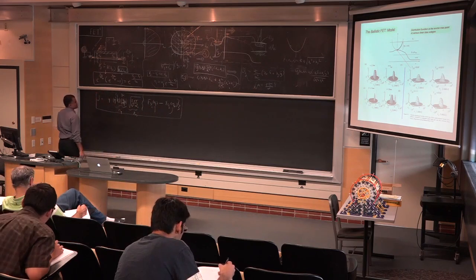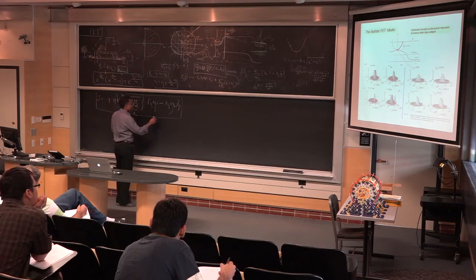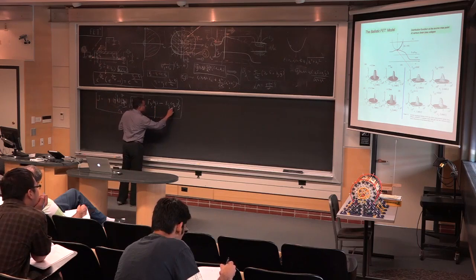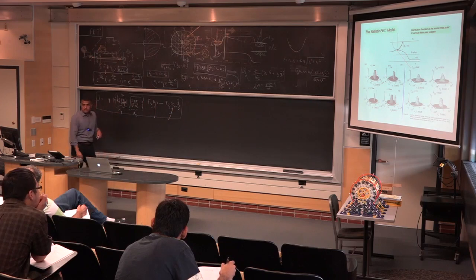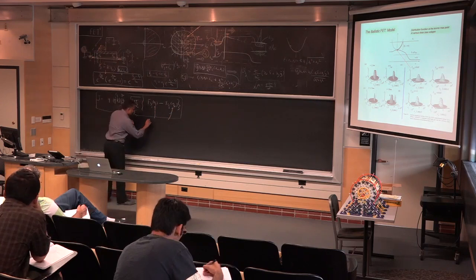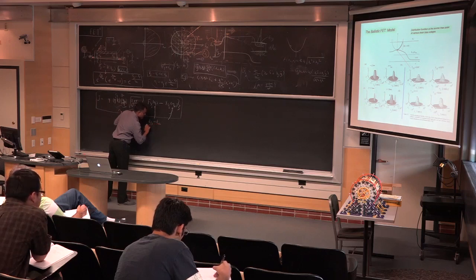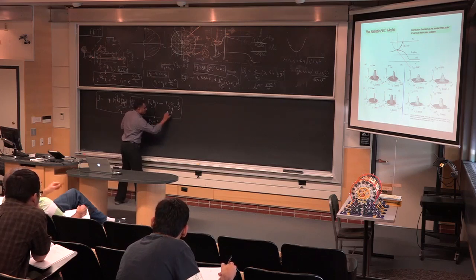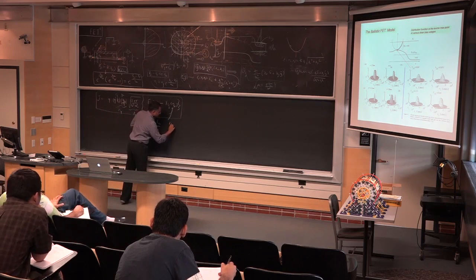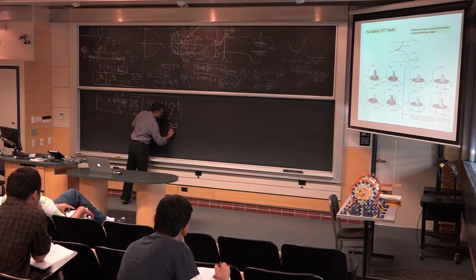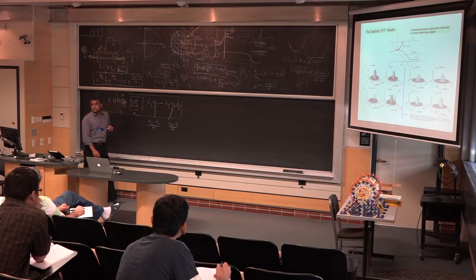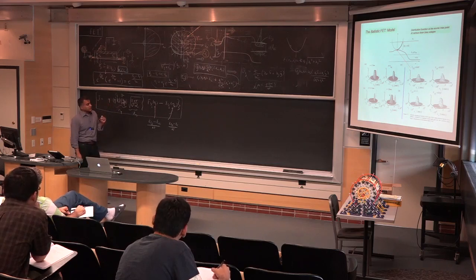And now the question really is, you give me an expression, but how do I actually evaluate it? You need to know these two quantities, right? What are these two quantities? Coming back again, eta sub s is the Fermi level of the source minus the conduction band edge, over kT. Eta sub drain is the Fermi level of the drain minus the conduction band edge, over kT. Right? This is in pictures.